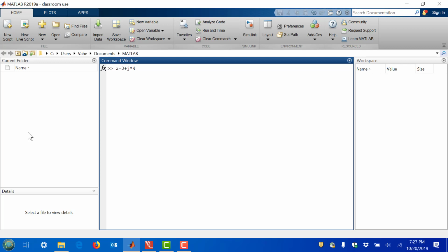We know it's a complex number. And once we enter it, you'll see that MATLAB recognizes it. The only thing you'll see is that MATLAB will reply with I, because MATLAB recognizes I and J, but it will always reply with I. So just note that. Also, it writes the I after the number instead of before the number like we do for our notation.